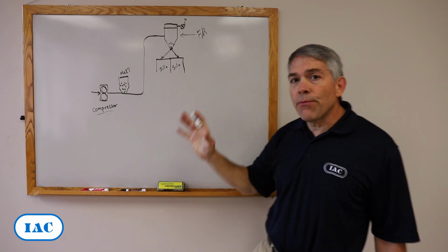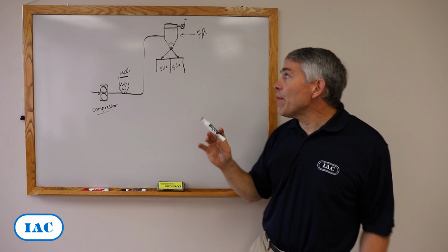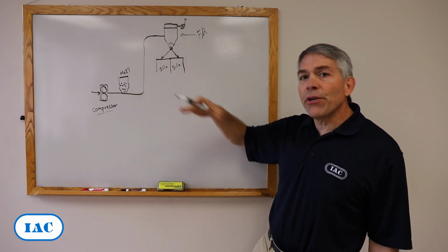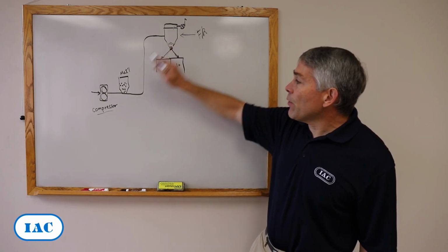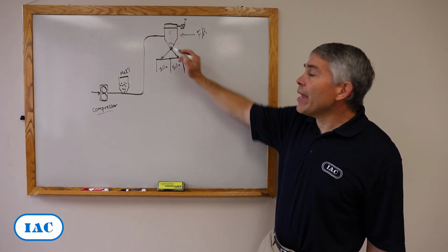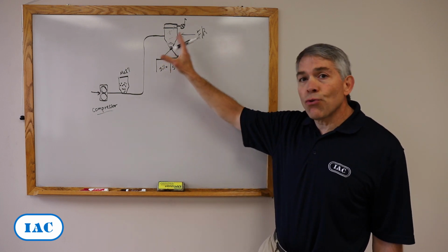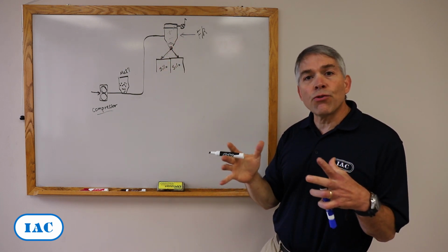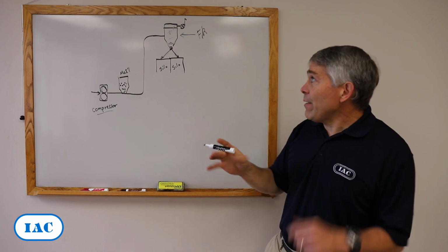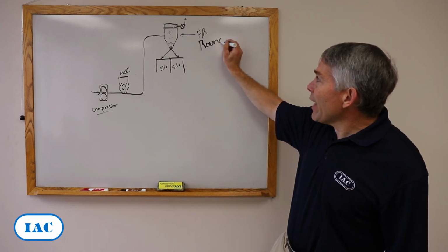A filter receiver has a round housing, and that's important because the pressure in this case is very variable. If you have a fan here and a compressor here, this can go positive and this can go negative pressure, and it's okay. The thing is that this device must absorb those pressure fluctuations without deforming. So basically, bottom line, a filter receiver has a round housing.